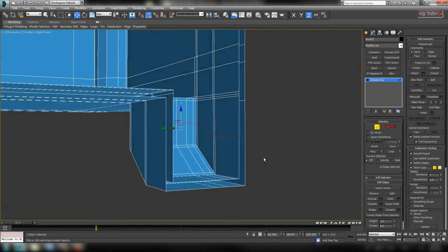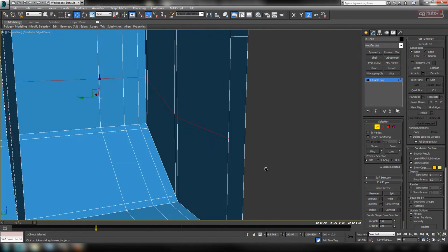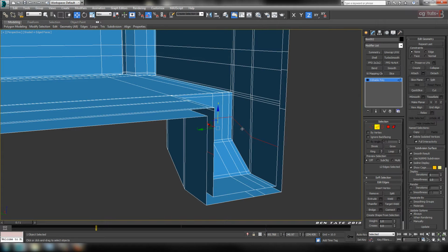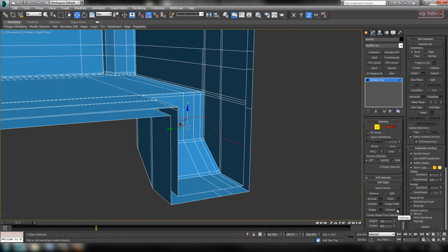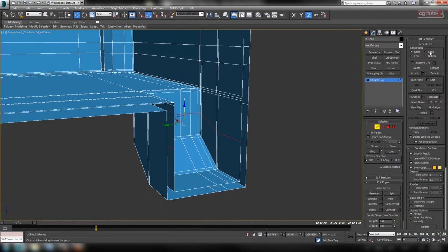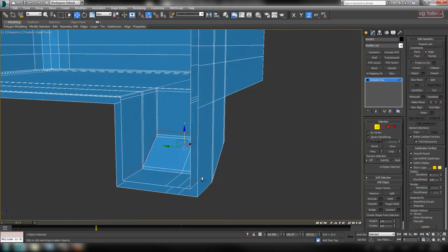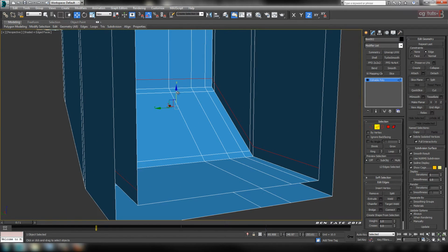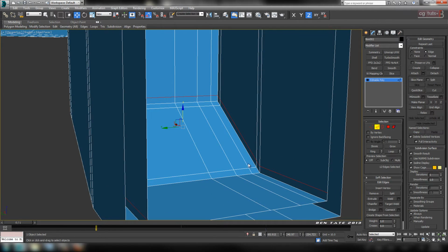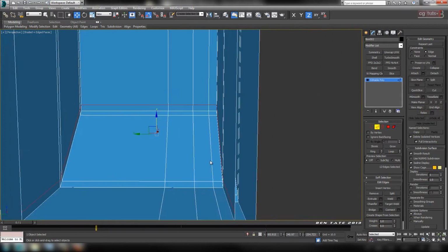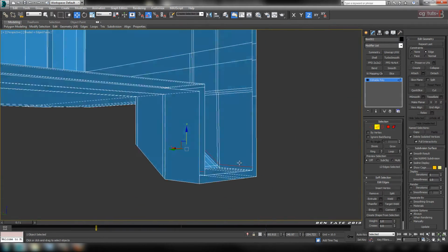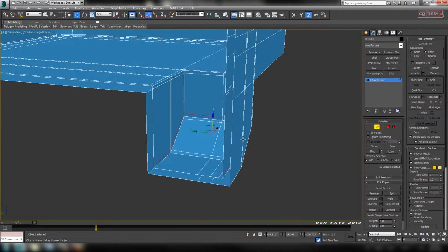I got an email from a couple of guys about a great tip for lining up your edges when you're doing support here, rather than trying to crank it down with the connect and then line up the verts manually. If you put on the edge constraint, you can actually just drag the edge loop down until it touches the bottom loop, let go, and then just pull it up, and it'll take on the exact form of the bottom polygons there, which is super cool and something I really never knew about. So thanks to Matthew and Spaex, I think that's how you say it, for that tip, because that's super useful. And that makes things a lot easier than manually adjusting the loops by hand. Okay, so we have that supported.